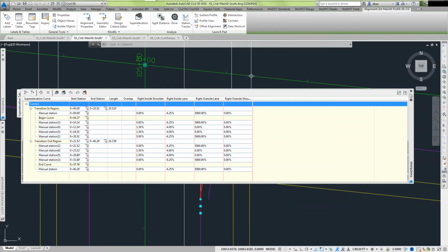All right. Now, one last word about the assembly and the sub-assemblies. In this case, you can't use standard curb sub-assemblies because they don't apply or allow you to enable super elevation. They're just curb, and we need a different behavior. Okay, so again, that's our Super.